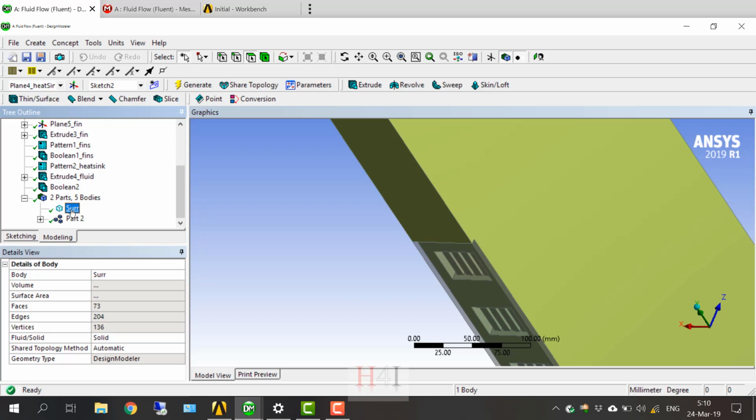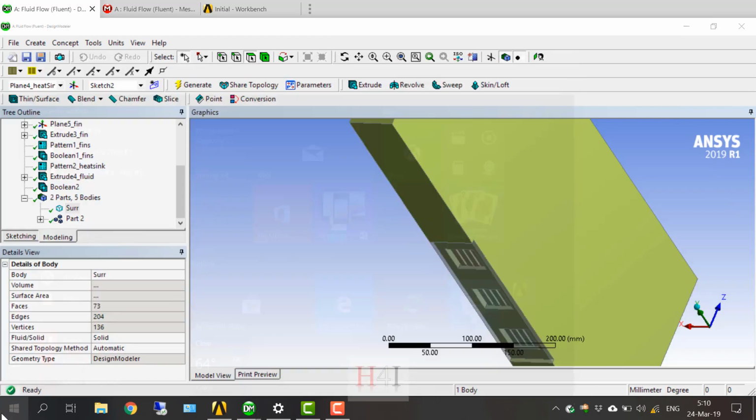Okay. Will you define a new connection between fluid and solid? Yes. The interface. Yes. The interface is defined for you automatically in the mesh. I will show you later. But I delete this definition and define it myself to be more sure about the definition, because sometimes it gets it wrong. You define it in the mesher or in Fluent? I start from the meshing application, then I define it in Fluent. I will show you the steps.